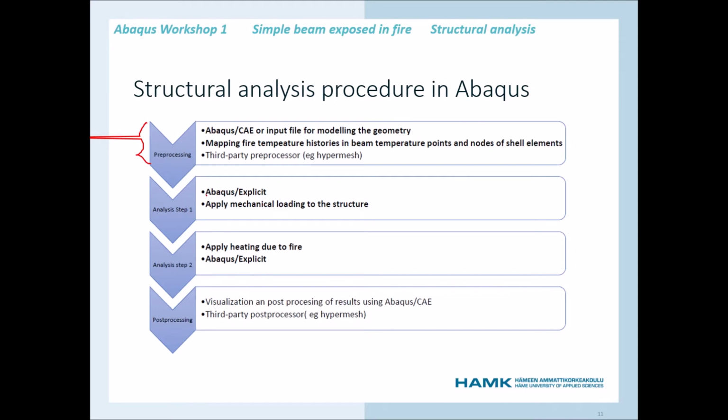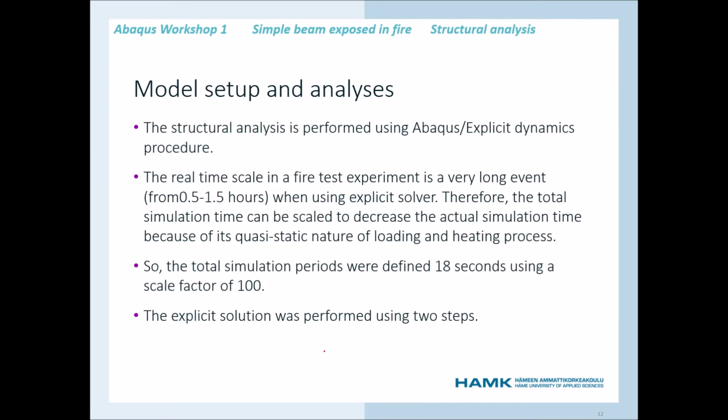So two explicit dynamic analysis steps are needed. In the first step, we apply the mechanical loading to the structure, and in the second step, we apply heating due to fire, and then finally post process the results.